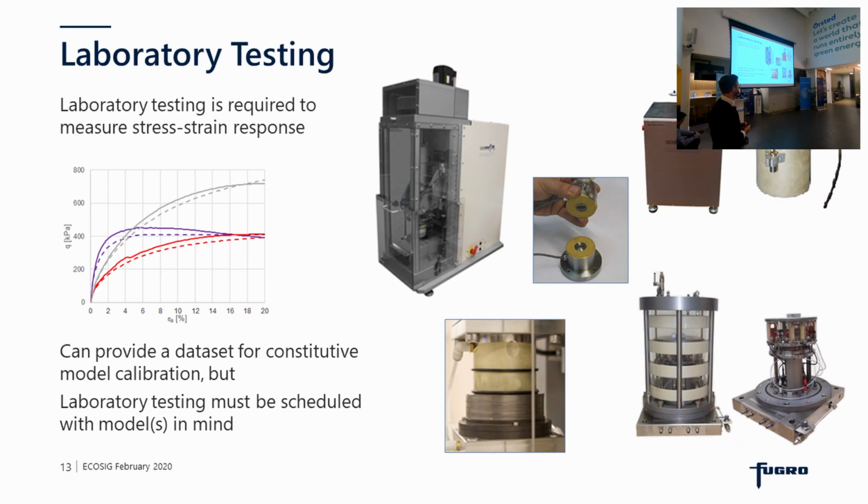There are certain in situ measurements that you can make, which will characterize the extent of soil response, so at the very small strain stiffness end of the response, or at the very large strain, essentially failure state of the soil. But tracking the generation of the stress-strain response between those points is tricky to do via an in situ test. Perhaps a pressuremeter gets you the closest to that approximation. But otherwise, we need to generate significant laboratory testing data sets in order to characterize that stress-strain response.